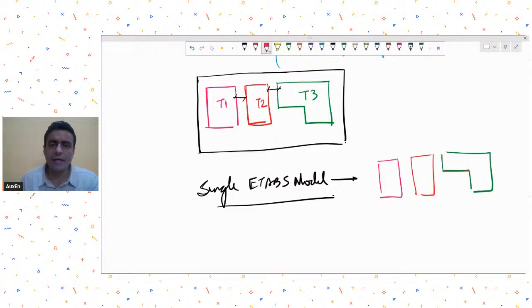So as you know that time period, usually even now as per the IS 16700, we are allowed to use the time period as calculated by the software, that is based on the basis of actual mass and stiffness. So time period calculation can be a problem even if, let's say, you are using the approximate time period formula. For example, in the Indian code for tall buildings, the formula goes something like this.